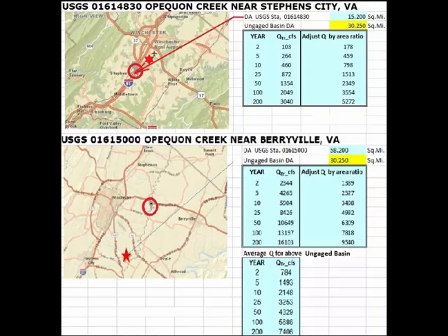The VDOT Drainage Manual outlines procedures for transposition of design discharges from one basin to another basin with similar hydrologic characteristics. Thus, the design discharge for an ungauged watershed is a direct ratio of the corresponding peak discharges for the respective drainage areas raised to a power for the desired flood frequency for nearby gauging stations. Peak discharges for each of the 2 gauge sites are obtained separately using the Log Pearson III method. The area adjustment exponent may vary from 0.8 to 1.0.